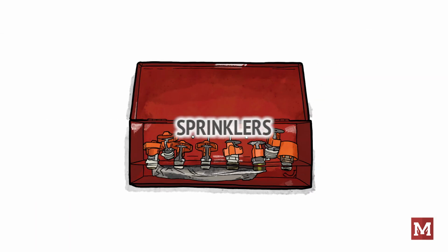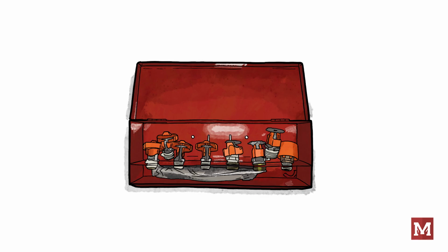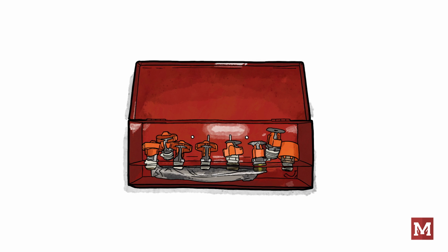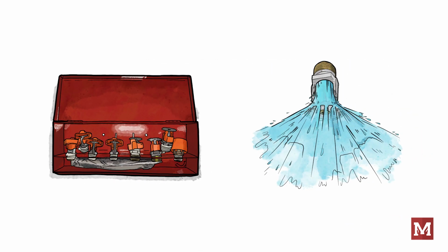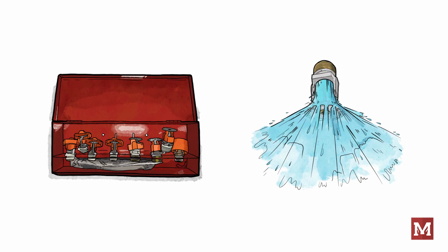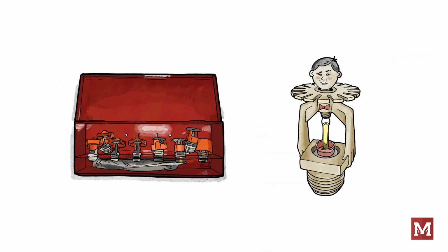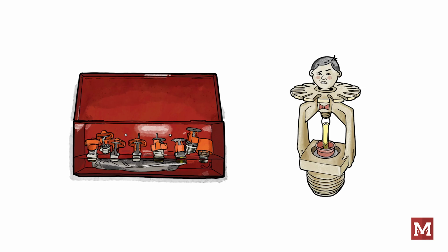Sprinklers. Too many times it seems that sprinkler selection is an afterthought. Really, this is where the rubber meets the road. These little appliances are what puts the wet stuff on the red stuff, as we used to say in the fire department. In our industry, a lot of people refer to these as sprinkler heads or just heads. Earlier in my fire protection engineering journey, I worked in insurance loss control. My mentor and the VP of engineering was a very respected member of NFPA 13, and he would reject a loss control engineering report if I used the term sprinkler heads or heads, because those terms do not appear in NFPA 13. So, for the purposes of me teaching these segments, I'll use the term sprinkler, old habits and all.